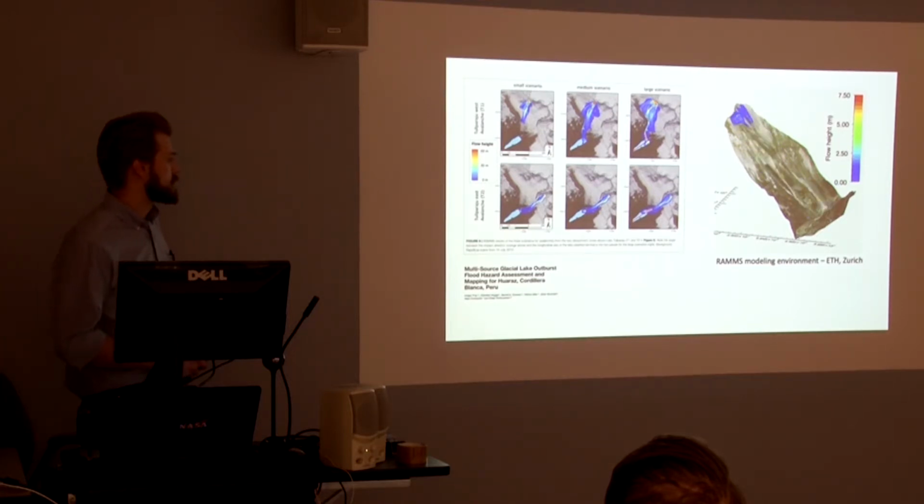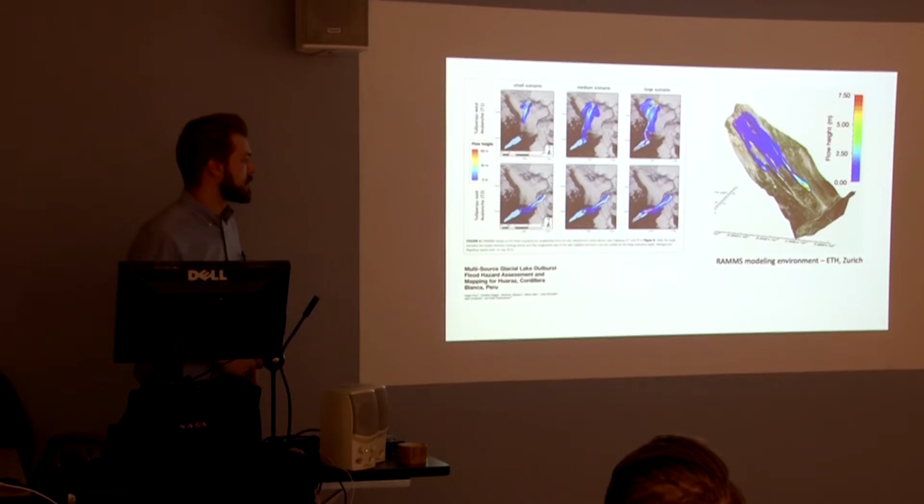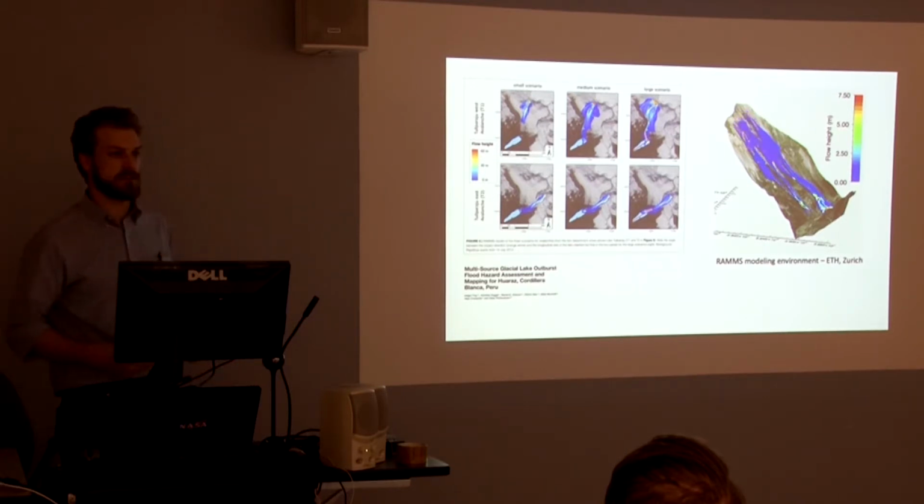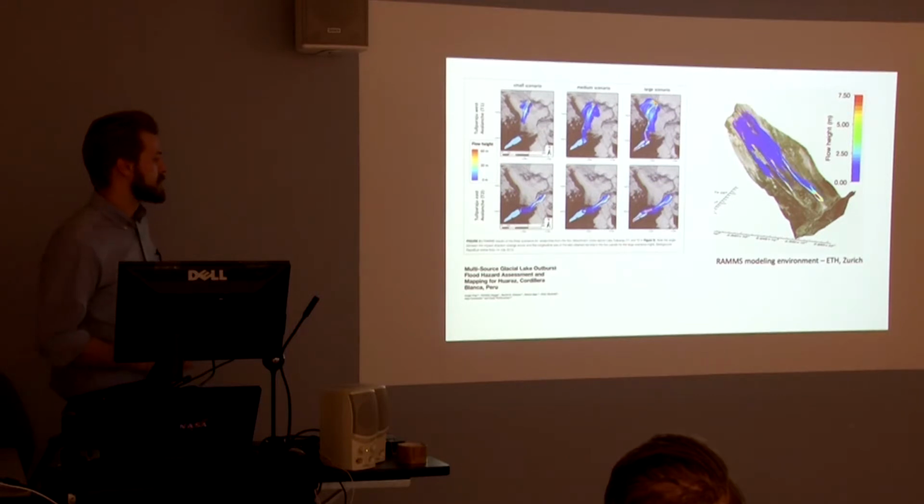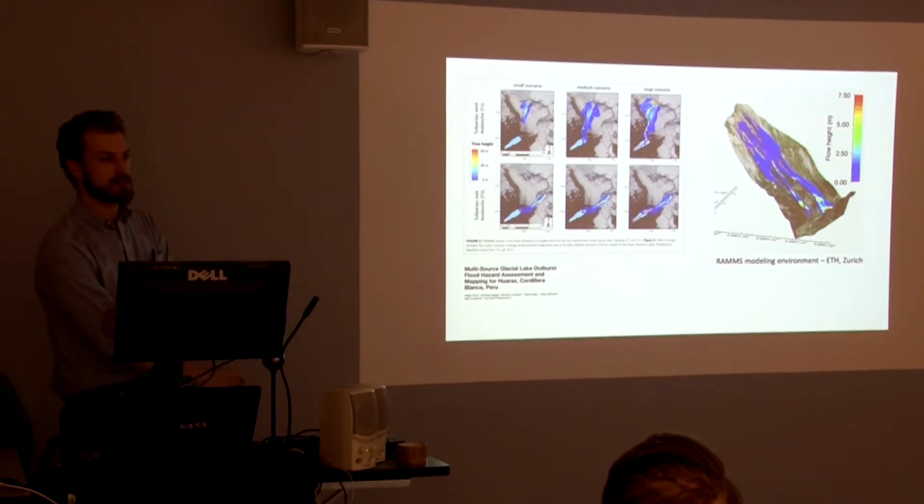And the resolution of the digital elevation models that they use also sort of dictates the flow. In this area, the only sort of continuous or contiguous data that you can get would be ASTER or SRTM, both of which are available at 90-meter resolution.